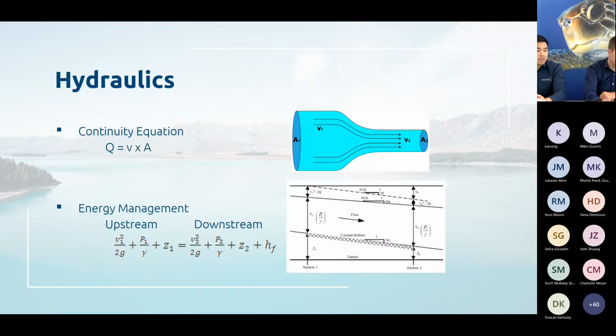Thank you. So we're just going to go through some of the basic hydraulic principles. You're probably quite familiar with a lot of these when you're designing a reticulation system. But just remember that designing a treatment system is pretty much the same as designing a hydraulic node or hydraulic structures. So the considerations stay the same. As you can see on the presentation there, one that we look at is the continuity equation, which is that flow is a product of velocity and the cross-sectional area.